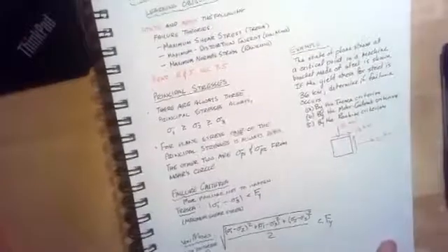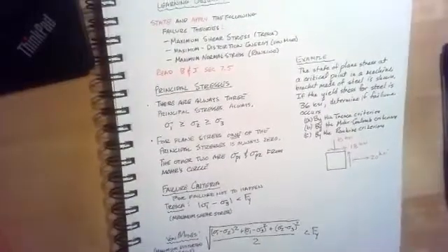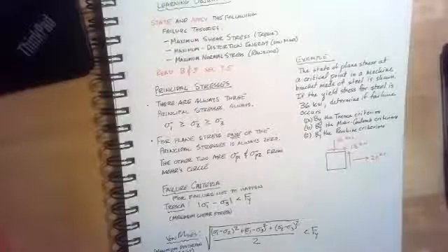So principal stresses, there are always three of them. Sigma 1, Sigma 2, and Sigma 3. And for plane stress, at least one of the principal stresses is zero. So one is always going to be zero. You could have others, but the other two that we're going to get are going to be Sigma P1 and Sigma P2 from Mohr's circle. We just order them Sigma 1, Sigma 2, and Sigma 3, where Sigma 1 is the most tensile stress, Sigma 2 is between Sigma 1 and Sigma 3, and Sigma 3 would be the most compressive of the three stresses. That's a common, consistent convention.